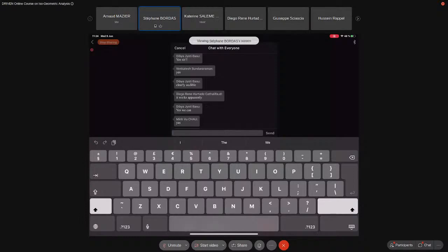So in your question, I see 2 parts. I see one part is if you move the control points, you should make sure the geometry does not change, first of all. And that is possible. There are algorithms that allow you to increase the number of control points without changing the geometry, which is not obvious that this is possible. So you can add control points, not even talking about making the knot multiplicity increase, but you can actually add actual control points without changing the geometry. So that is doable. We did it.